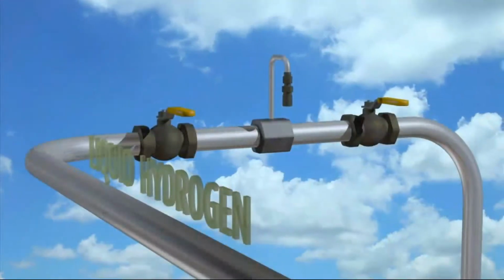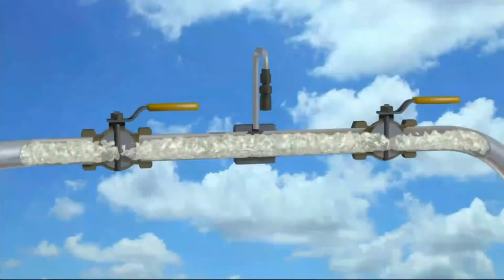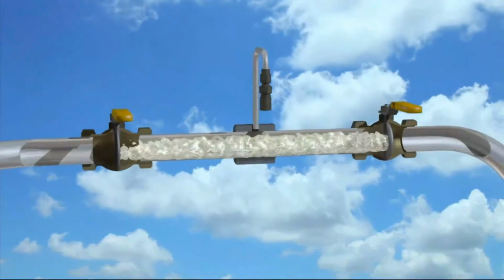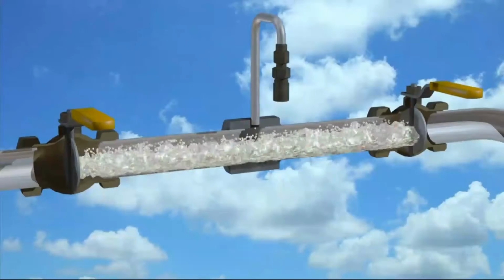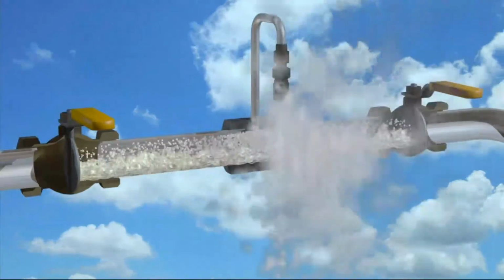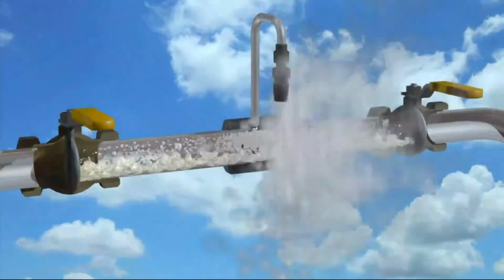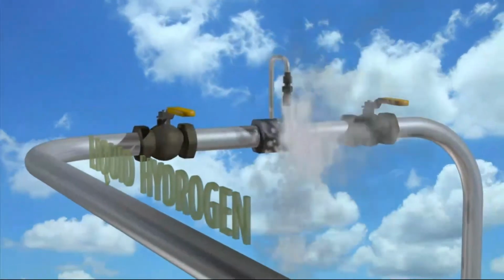If liquefied hydrogen is trapped in a container or a pipe with no venting, you've got the same situation. Even though it's very cold, liquefied hydrogen is actually boiling as it evaporates. This can build up tremendous pressure, enough to cause piping to rupture. Safety relief devices must be installed in all piping and storage systems, between all block valves, and anywhere else that liquefied hydrogen may become trapped.